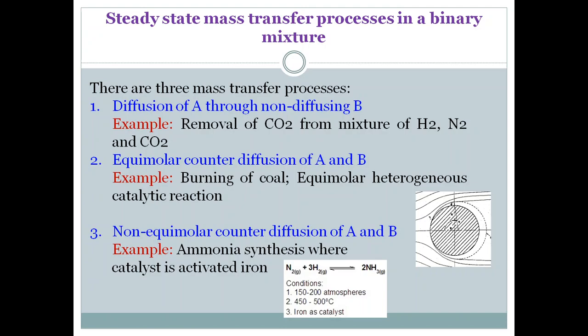Therefore, it is very important to design the equipment under steady state, because plants will run at steady state. Yes, initially there will be unsteady state, but for 1 day or 1 hour it will be unsteady, then the remaining 330 days it will be steady state. That's why in chemical processes most of the calculation we do under steady state condition.